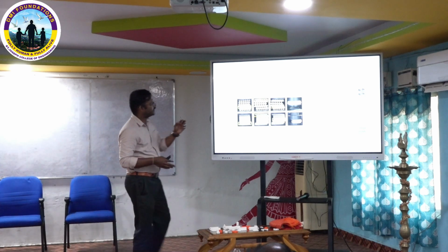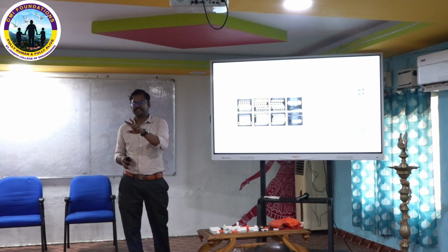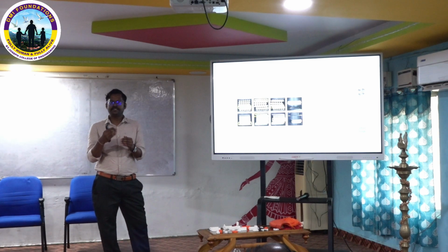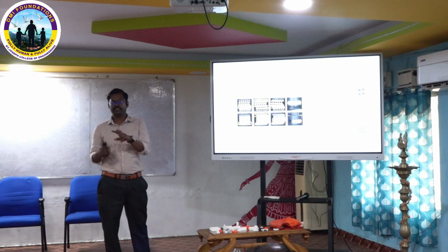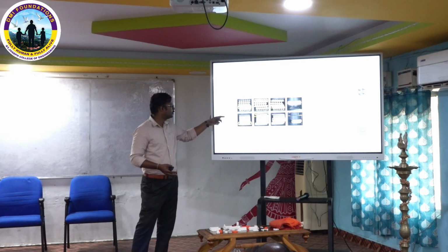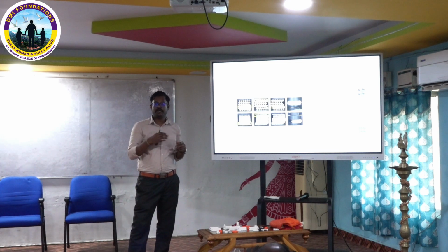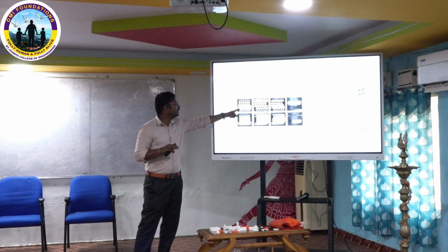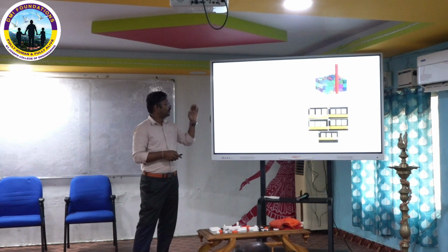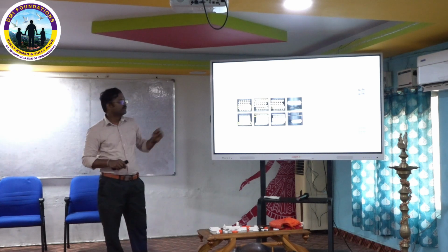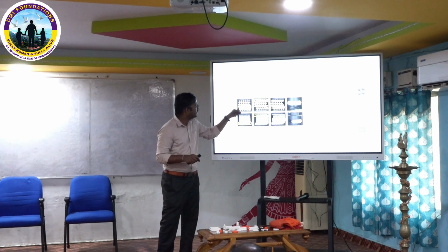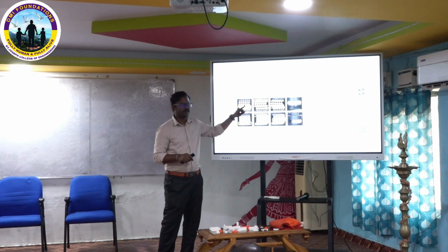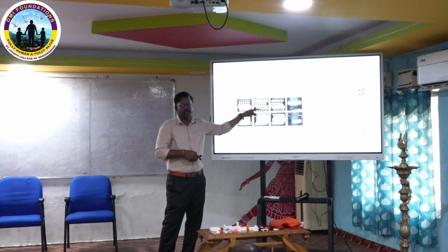In the analysis, I get only one or two lattice structures showing different properties. Other things, based on the relative density and strain rate, give the same properties. Only 2 structures showed different properties. These 2, simple cubic and redundant, deformed in the same manner. Bending happened here, but before bending, because of the vertical orientation struts and horizontal, even though it is a bending dominated structure, it deformed as a stretch dominated structure. But you can see it came out of the boundary, right? This kind of deformation we observed.